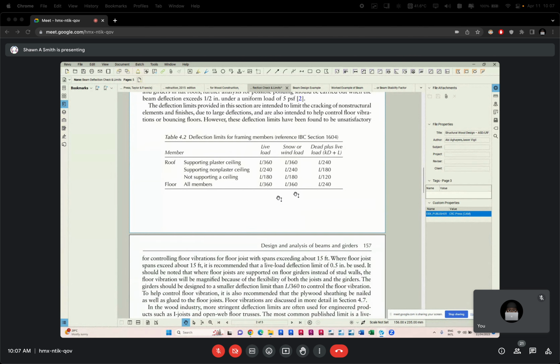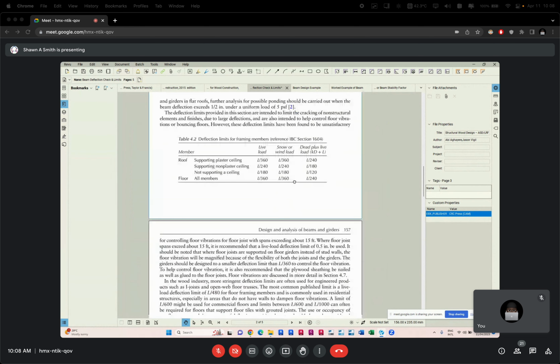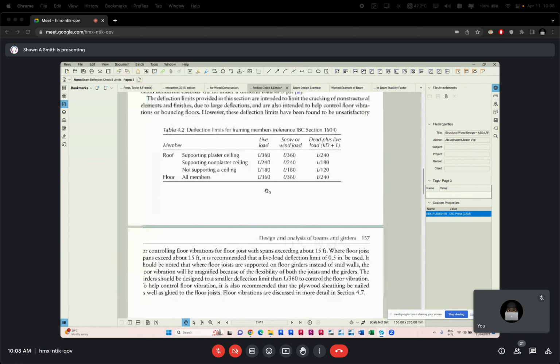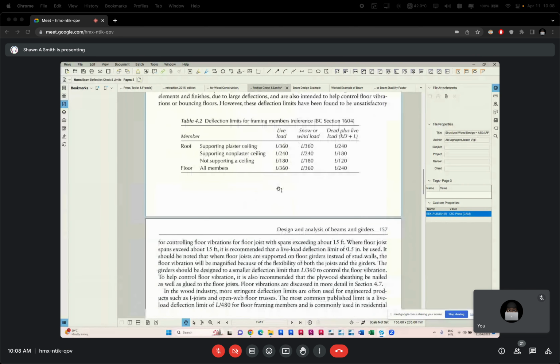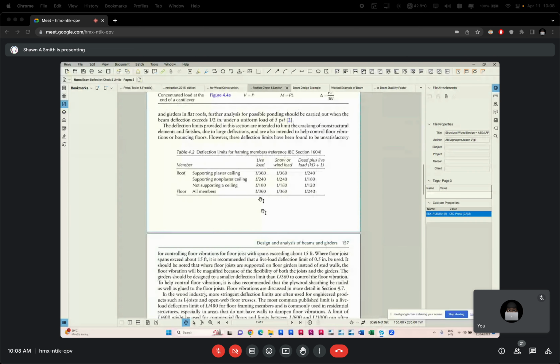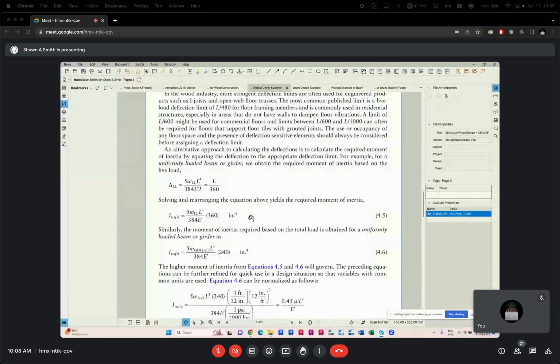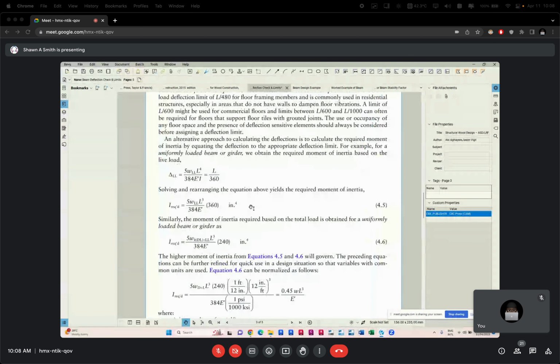And that way, the deflection becomes lower. Or we can double them. We can double the timber members, put two beside each other. All right, but that's already done in Jamaica. We don't have the kind of economy for that. So we prefer to increase the size a bit or space them a bit closer. There's much more economic gain there. All right, class?